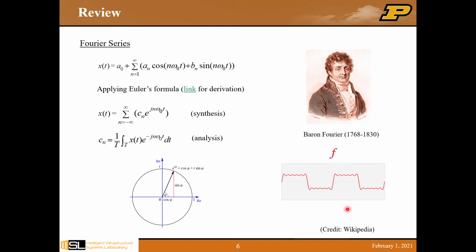By applying a series of sine and cosine functions, it represents the square signal. The more terms you add, the closer the summed signal is to the square signal. The stem plot here shows the frequency domain values corresponding to the square signal.